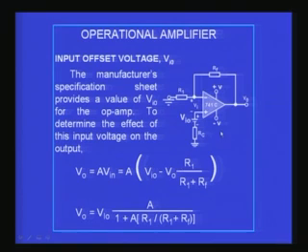That is, we are trying to calculate what the input voltage will be if I have VO at the output. So, VO is multiplied by 1 by the gain, where (R1 plus RF) by R1 is the gain, so it is inverted here to R1 divided by R1 plus RF, and this gives you the input voltage corresponding to the output that you measure. The combination of this is what you will measure as the output.